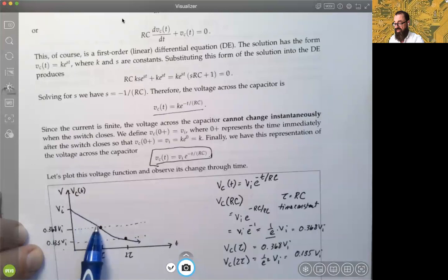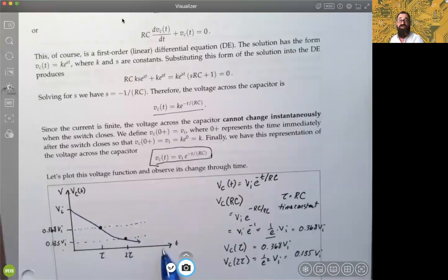The slope starts flattening out as you get through so many time constants. And in general, what people are interested in is how many time constants until you're essentially discharged. There really isn't hardly anything left, okay? All right, much like your garage door opener, once you close the switch, you can imagine the garage door eventually comes down and shuts, then eventually you need all the power to be dissipated totally, okay?